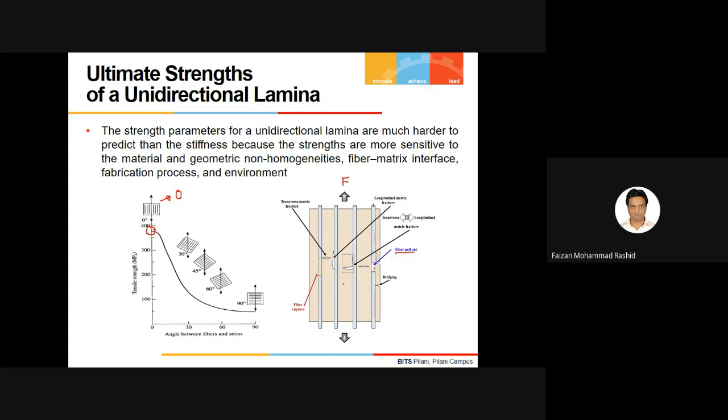So that's what I'm telling you. When you see that the composite material has failed, it is very difficult to say which thing actually caused the failure of the composite material as a whole. And this was not the case when I was having my alloy. If alloys are there, like aluminum or steel, and there is a failure, I will find that some crack has initiated somewhere.